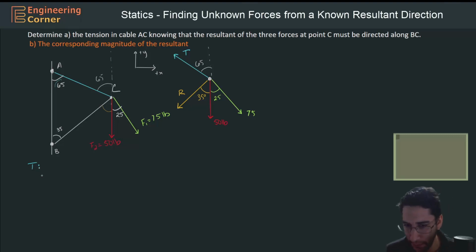For my i component, you just need to be careful because for whatever reason, students always want to say that X goes with cosine, but it doesn't. It goes with whatever component of the triangle is in the horizontal direction. In this case, if you use SOHCAHTOA, you'll see that this is going to be the sine. We know the tension, and to get this horizontal component, we need to use the sine.